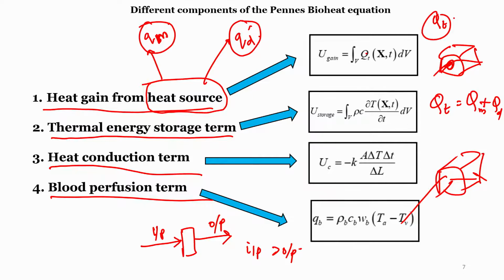That is the thermal energy storage term. Fundamentally, that will mean mCp dT only. The measure of that energy would be mCp dT, and if you want the power, we can divide it by time, dt. Power means we get the rate of change of that stored energy as a function of time.